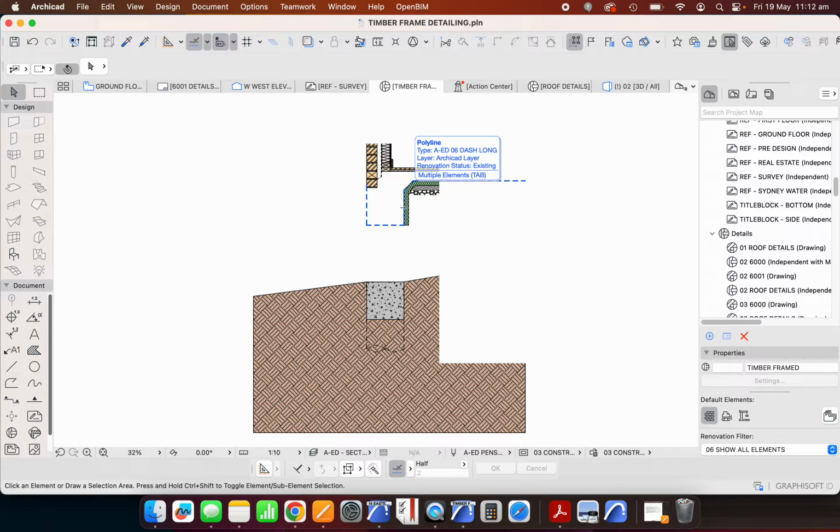What we may want to have is a damp-proof course between the concrete and the brick wall, or partly up the brick wall, or maybe further up here. And that's to stop moisture, damp, from rising up through the ground and up into the bricks. Now, again, we could achieve this also by putting a membrane underneath that strip footing. Again, it's just not very common.